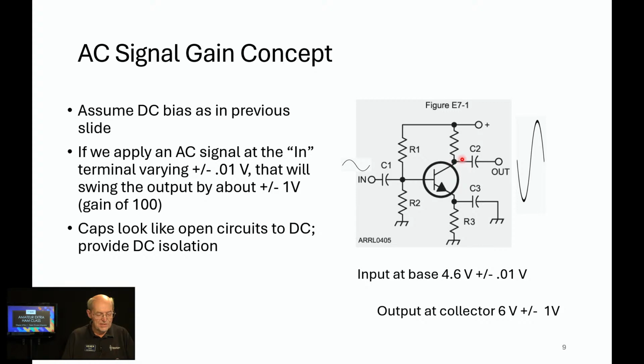Notice that these capacitors, the way they're drawn in the circuit, are one right above the other. And for the purpose of our pool question, when it asks what kind of amplifier this is, that's the shortcut that you can use to say, oh, this is the common emitter configuration. If you wanted to know from an electronics point of view, you'd have to figure out that the input and the output share the emitter.